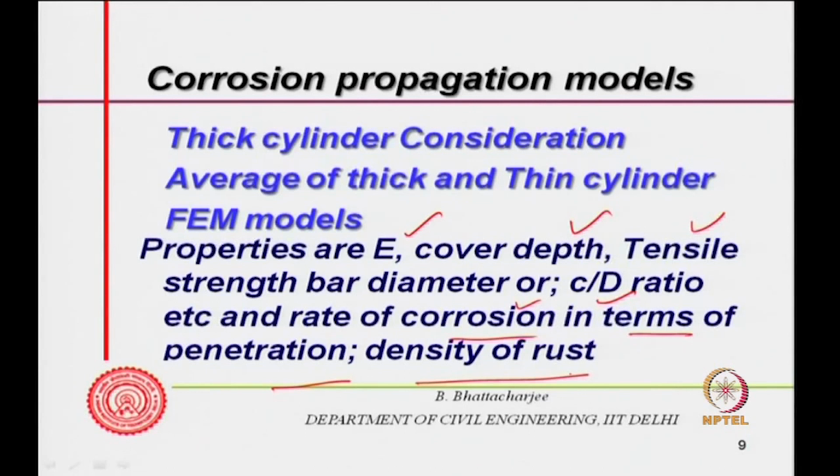That is relatively much more sophisticated than what we just talked about. Those were empirical models, while what I am talking about right now is also empirical, but based on theory of elasticity, a mechanical model of cracking of the cover concrete. So, if you want to estimate cover cracking, this is how one can model it.